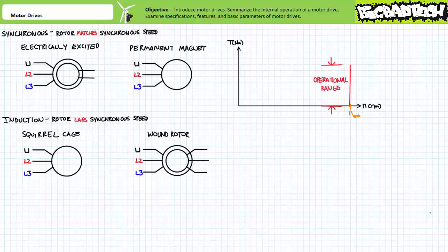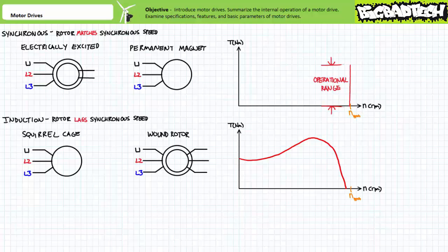The rotor of a three-phase AC induction motor, in contrast, must necessarily lag behind the rotating magnetic field produced by the stator for the induction process to work at all. The rotor speed of an induction motor therefore has a more complex relationship with synchronous speed that must take into account applied load. The speed-torque curve of a generic induction motor shows that even at no load conditions, the rotor speed is slightly less than the synchronous speed, and when operated at rated load conditions, even less.